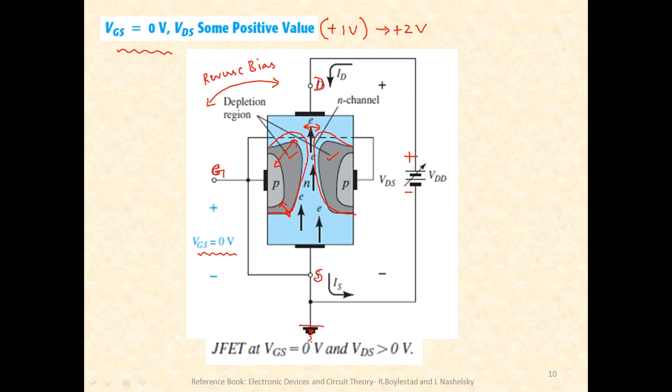See, this is called the width of the channel through which the electrons are passing. Okay, so as and when the width of the depletion region goes on increasing, the electrons find it very hard to move from source to the drain end. Okay, so the point is the resistance offered by the channel goes on increasing as the drain potential increases.